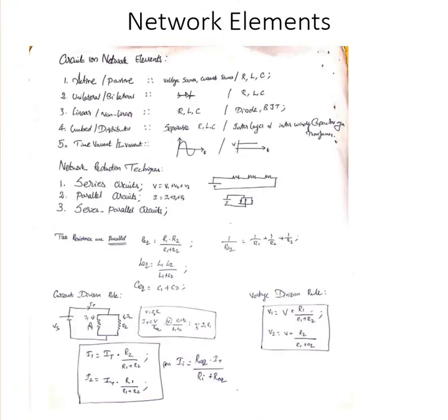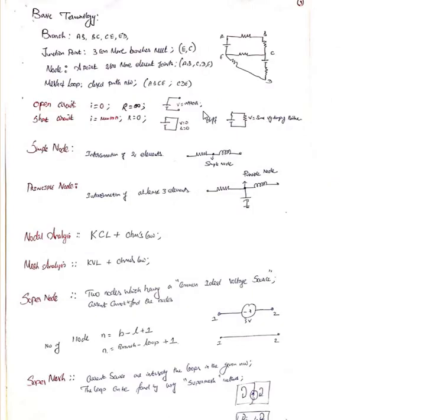I will show you one more slide. Here I have to show you: this is an open circuit and this is a closed circuit. In an open circuit, the current value is 0 and the resistance value is infinity. In a closed circuit, the current value is maximum. If you close the circuit directly, without a lamp or resistance, it is called short circuited, so the source is directly shorted. I am showing this for understanding purposes, but in practice you will connect it with a lamp or resistance.